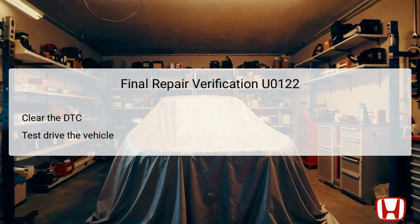During the test drive, monitor the dashboard for any warning indicators and watch for proper vehicle behavior, especially regarding the stability assist functions. If everything operates as expected and no DTC is re-registered, this indicates a successful resolution of the issue. However, if the DTC returns, it may imply that further diagnostics are necessary, possibly requiring a deeper examination of the network communication components.